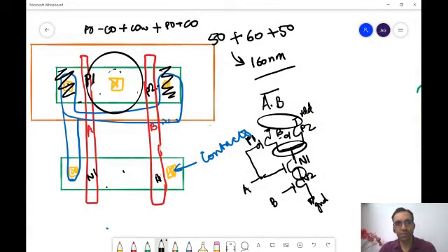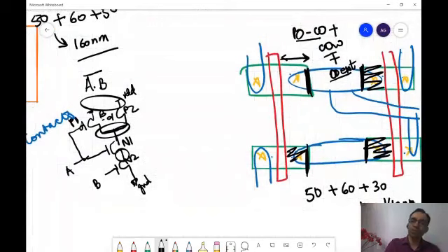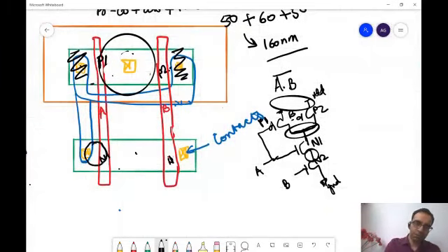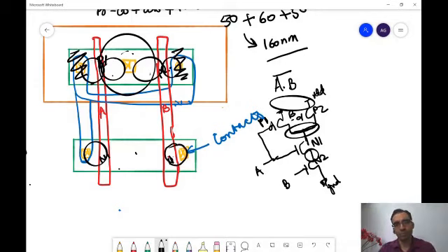So diffusion capacitance would reduce drastically. Diffusion capacitance reduces not just because of area getting reduced, it also reduces because the sidewall junction capacitance does not come. Right. Yes, sir. Additionally, how many poly to contact capacitances do you see now? 1, 2, 3, 4, 5, 6. 6. How many were there before? 8. So you see, you are able to reduce that capacitance also.